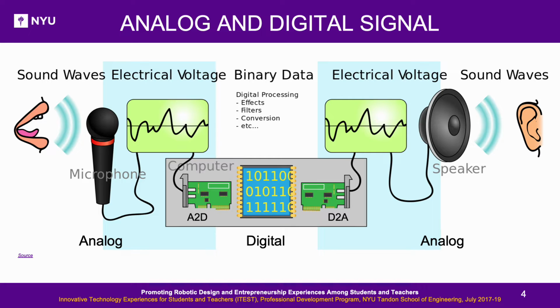On Arduino boards, analog pin labels, A0 to A5, are prefixed with an A to indicate that these pins can read analog voltages. The Arduino's ADC is a 10-bit ADC, capable of detecting 1024 discrete analog levels, which is 2 to the power 10. This means converting an input voltage from 0 to the operating voltage, 5V or 3.3 volts, into an integer value from 0 to 1023. For example, the Arduino Uno provides a resolution of 5 volts over 1024 units, or 4.9 millivolts per unit reading.